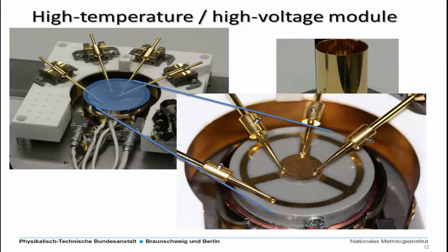As I told you, temperature measurement is very important for these length measurements, especially in the case if the material under test has a large coefficient of thermal expansion. Unfortunately, we are only able to measure the temperature inside the reference plate and not directly on the sample under test, which would be better, of course. There will be a gradient in this sample arrangement, and we were able to measure that this gradient is less than 5 Kelvin, but as long as we cannot measure it more precisely, we have this systematic uncertainty contribution, which is one of the largest at the moment.